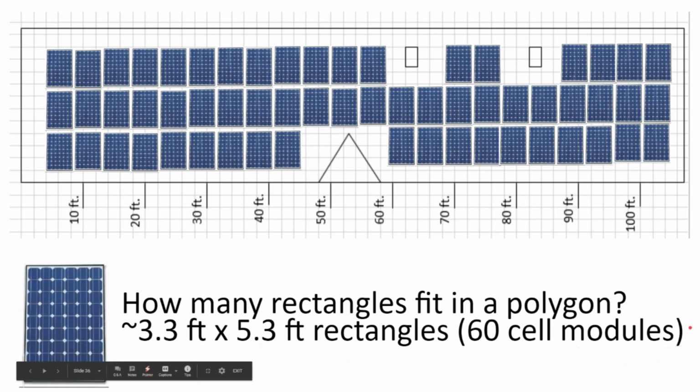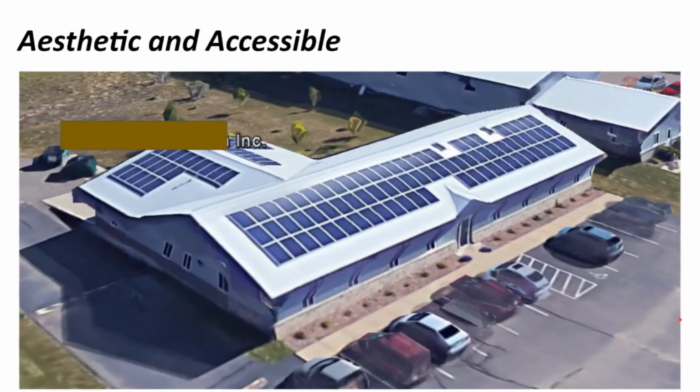So good roof surfaces that are rather large or boring, regardless of orientation, are good solar roof surfaces. Similarly, an east-west roof can be as viable as a north-south roof in terms of project location. I don't even mind a system which produces more electricity than the building consumes. You can always find a use for more electricity, such as reduced reliance on gas or wood heat in the winter.